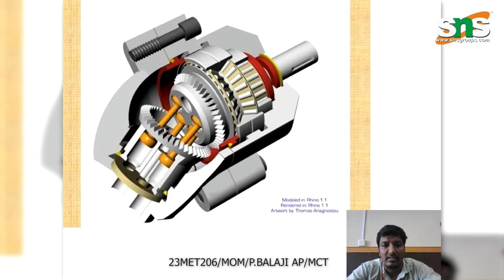On the screen you can see two gears connecting the pistons to the cylinder blocks. In the axial pump we have a single shaft plate connected to all the cylinder bores and pistons, but here the connection is made using pistons between the two gears. The two gears mesh at one end, and the rotation force on the shaft on the right side is transferred to the top gear.